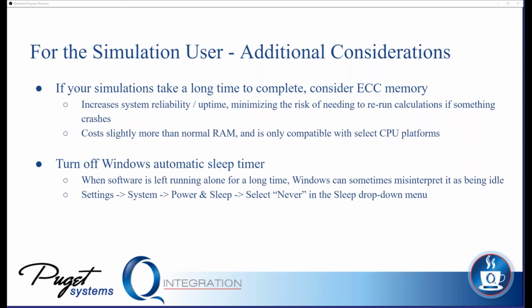But having ECC memory will reduce the risk of a memory error causing a blue screen or some other thing that interrupts your simulation and requires you to redo hours of work. It does cost a little bit more both on the CPU and the memory side. But again, if this is critical stuff, and especially if you have long things, rerunning a 20-minute test, not a huge deal. Rerunning a 2-day test, a big deal. So sometimes it can be worth spending a little bit extra there.